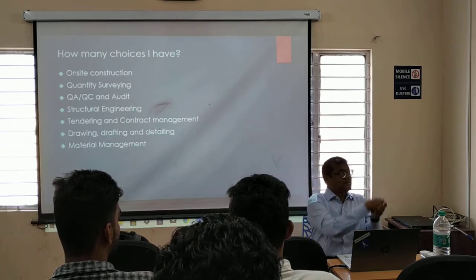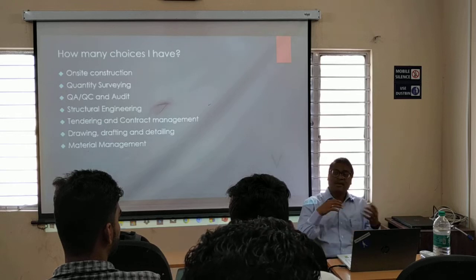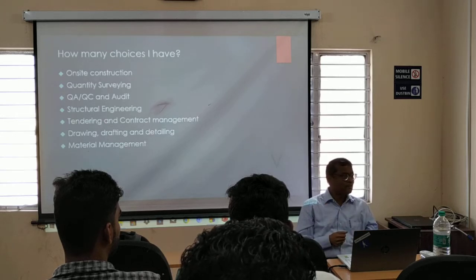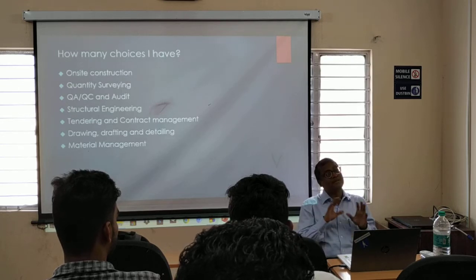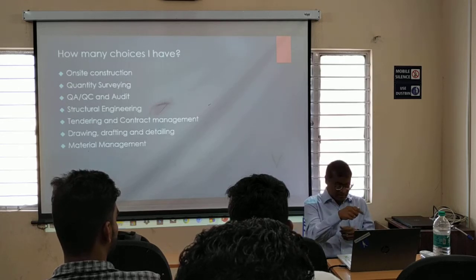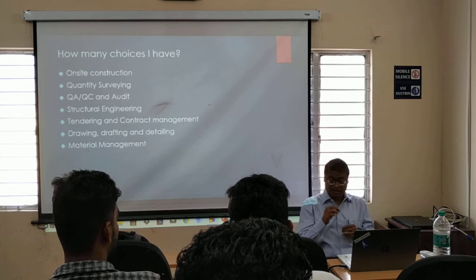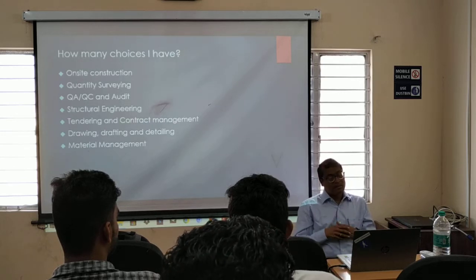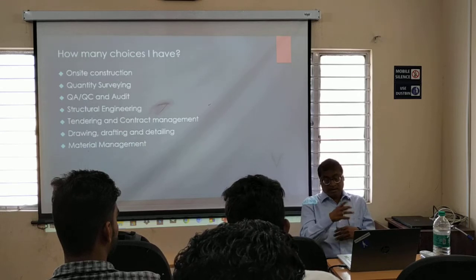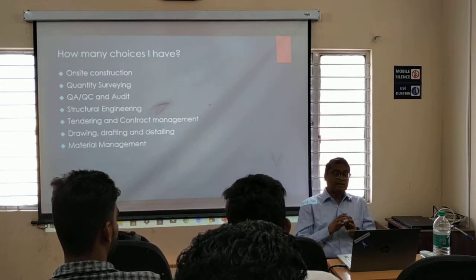Curing doesn't mean only pouring water. There are different types of curing. Spraying, you have to spray a sealant. There are various types of curing, and he is in charge of all that. I will come to that in the next slide. Steam curing, chemical curing, coatings are there, steam curings are there. So that I will come to later.